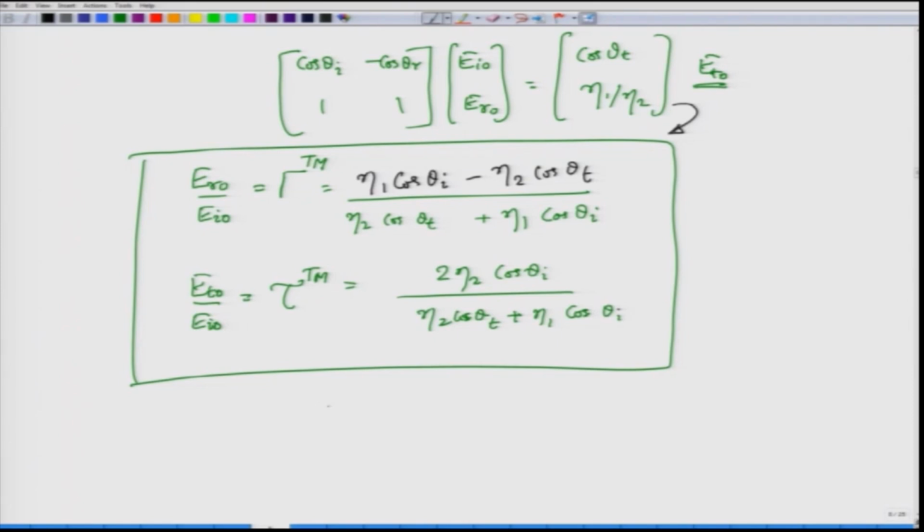And how do I do that? Well, we go back to the expression for eta. I will not tell you how this expression has come out, but if you go to any electromagnetic theory textbook and especially look at the chapter on plane waves or on the transmission line coefficient, you would realize that this wave impedance eta is given by free space wave impedance eta 0 divided by square root of epsilon r, where epsilon r is the relative permittivity of the medium.